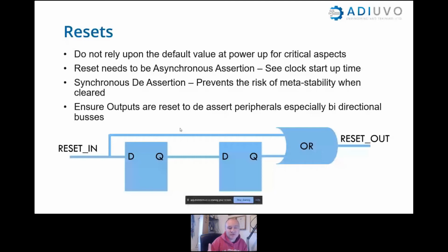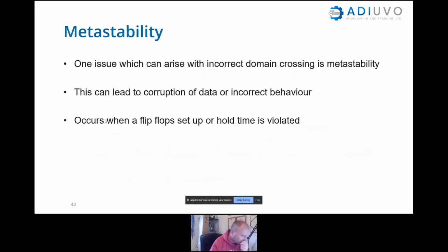So we need to make sure that we've got a good clean reset, that our reset takes into account any oscillator startup time plus a margin, and that when we deassert this reset, we're not likely to be causing the reset to occur near a clock edge, such that we can send downstream devices metastable. It's all nice and simple, but it's all these little things that pull together that make for a more reliable, better system.